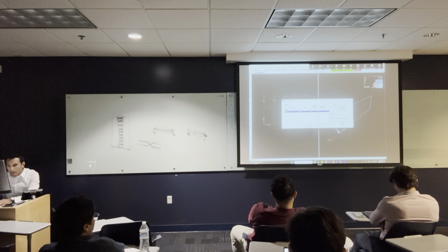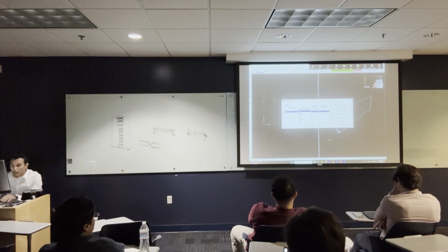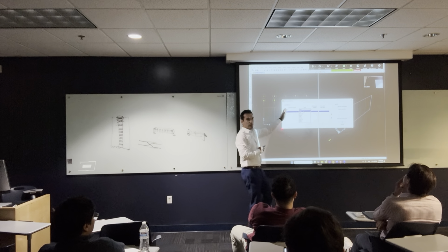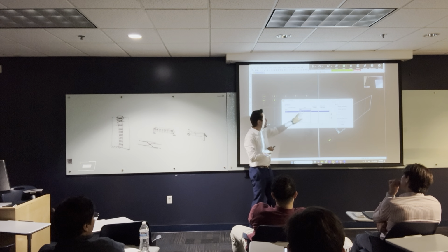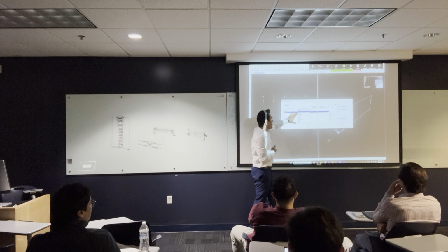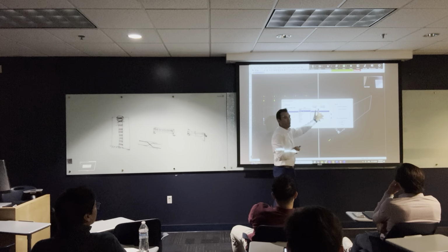So basically you come here, this is dead, it's called the load pattern name, and you can choose the load pattern type. You can pick a name for the dead load. You can name it own weight, you can name it whatever you want, but what matters is the type. So I'm going to name it dead, and I'm going to keep the type as a dead load, all right? And then it says here, self-weight multiplier.